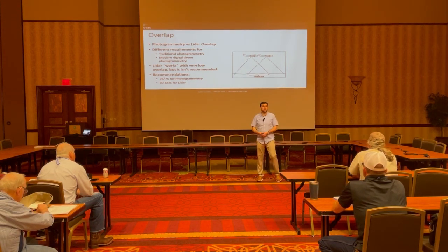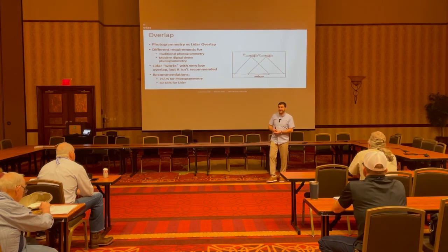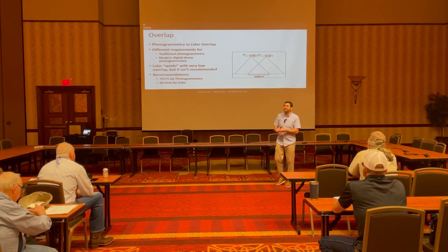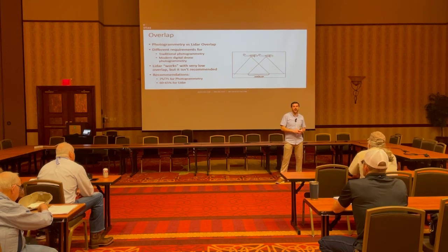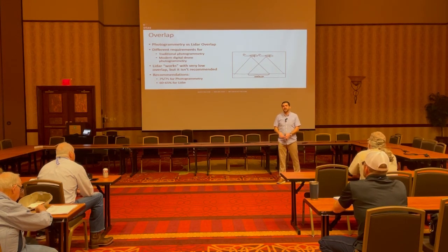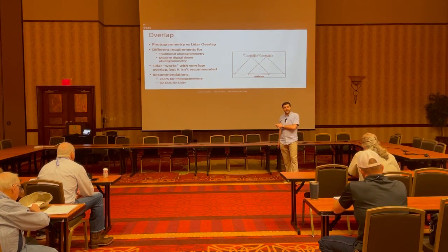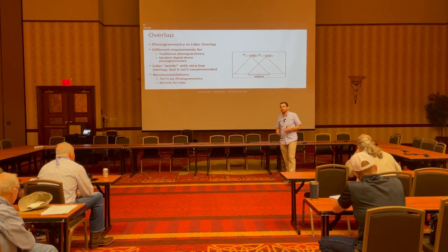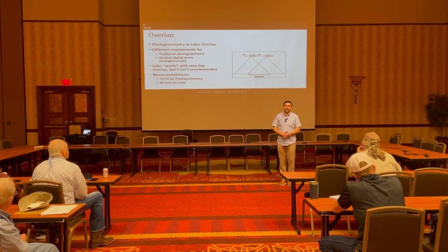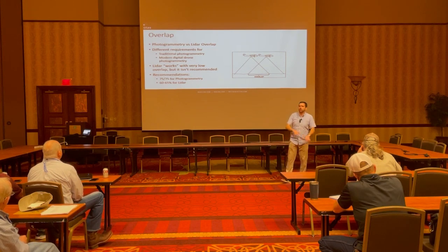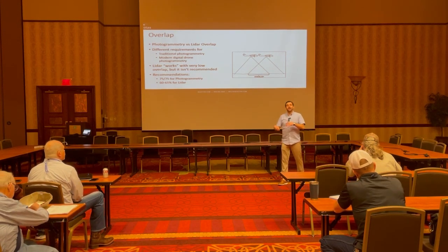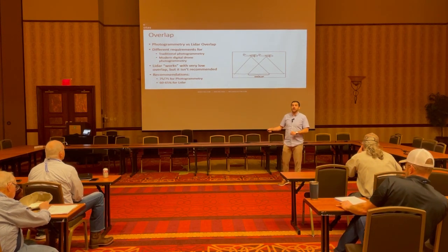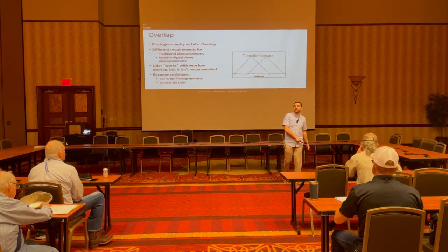And I say that as someone that's just been beating the drum of collect less data for a while, but with LiDAR, I actually like leaning a little bit higher. I've seen the most success in the 55 to 60% overlap on LiDAR, which does collect a little bit more data, but leads to a much more reliable workflow so that you know you captured the right data and you don't need to go out and fly the job site again. Again, that's one where the industry is still kind of coming to terms with it. Some people recommend very low. And you can get away with low overlap if you have really, really, really tight procedures.